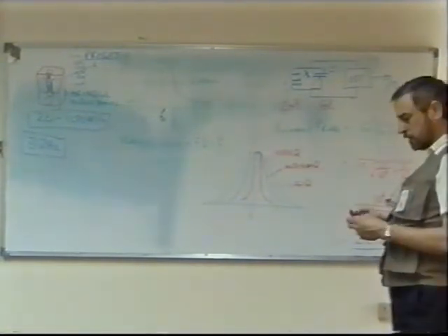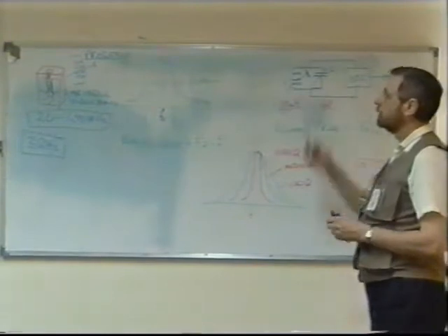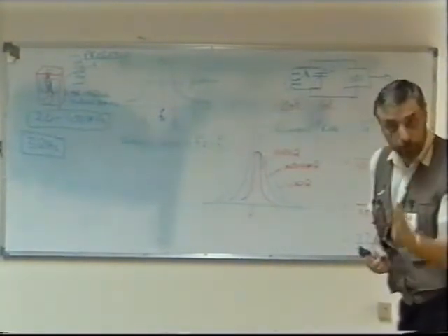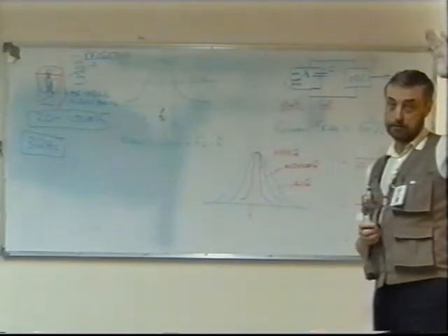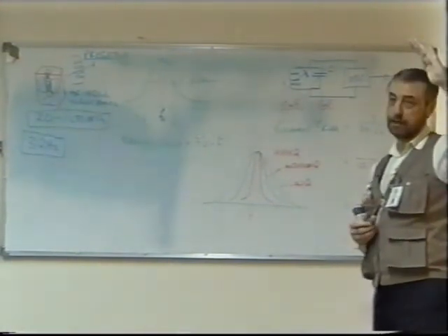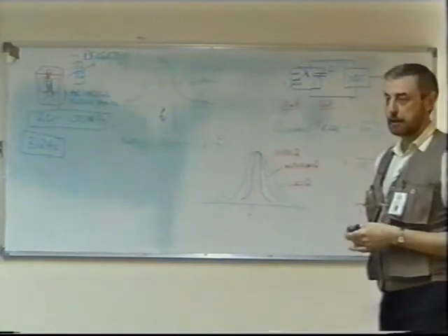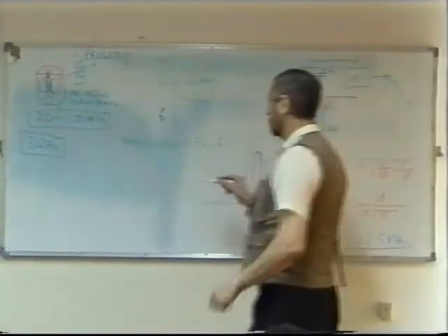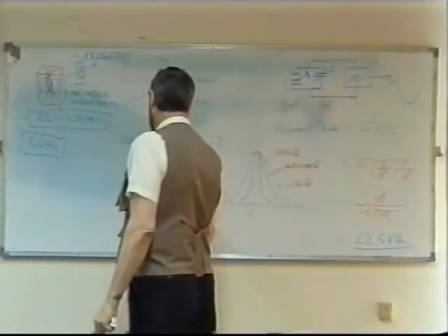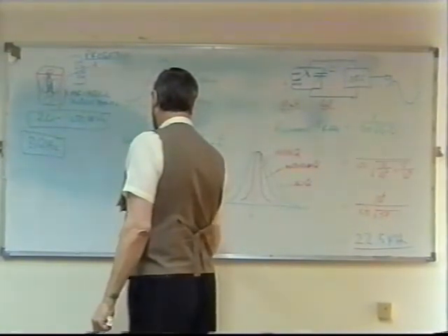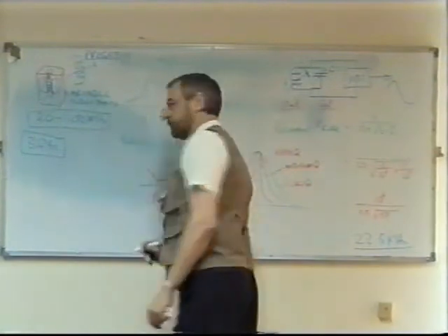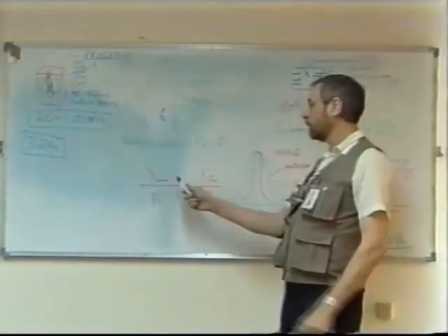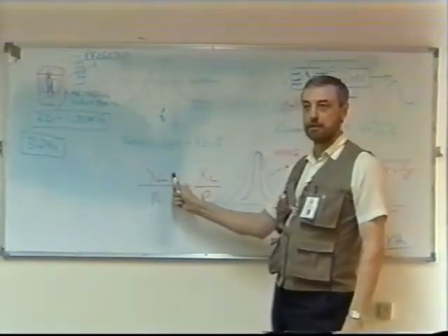But say I wanted a tuned circuit which not only had a certain resonant frequency, but also had a very, very high Q factor. Now a high Q factor, remember Q factor is XL over R, which is also equal to XC over R. To make XL big, what do I need the inductance to be?